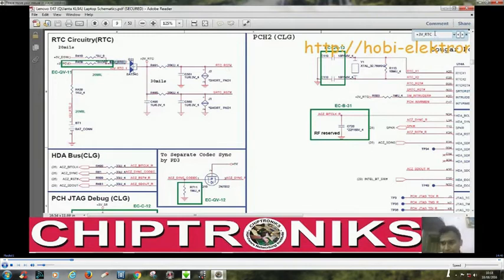So let's search for +3V_PCU. Obviously it will be coming from the 3V 5V voltage regulator. Once you start tracing the board according to the circuit diagram, then even if you don't have the circuit diagram, you can easily know from where this voltage would be coming. So where do I have to check from where this signal is coming? You get enough idea to trace a board, right?